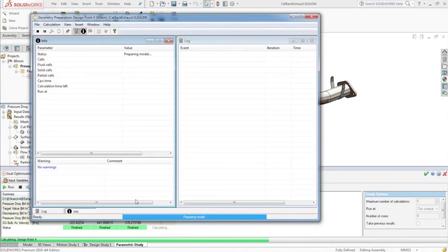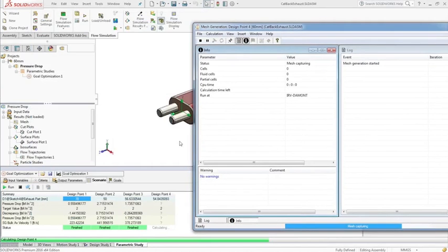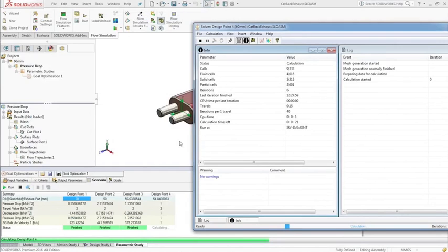You can see that the pressure drop on the 3rd try was 1.73 psi. So it's just kind of below our range. And so it's going to do one more attempt at about 54.5 millimeters. Maybe 55 if you round up.